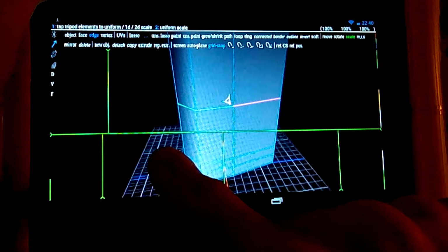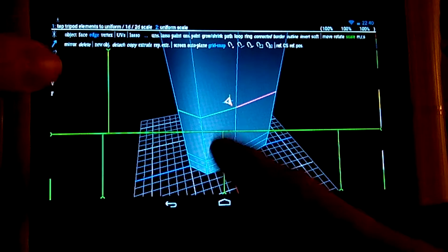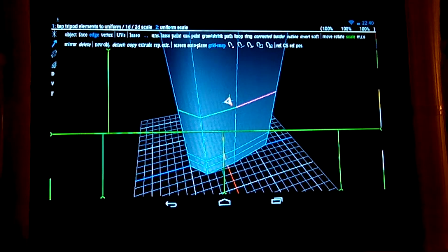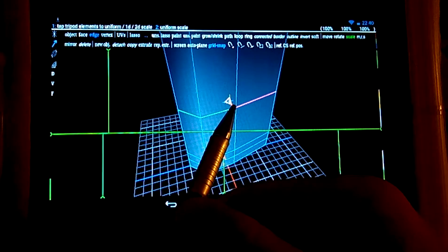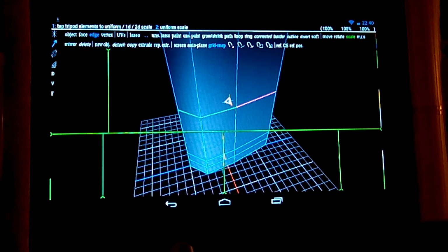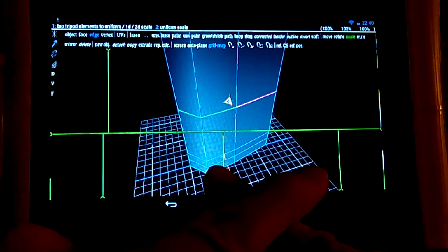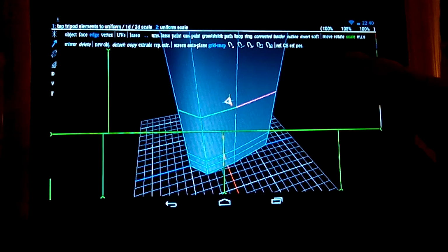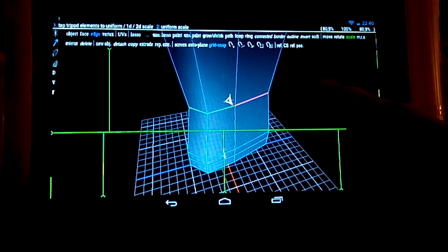Okay, I selected, maybe it's too little to be seen, the white line in the middle of the red and blue arrow. This will allow me to shrink or scale the section in the plane made by the crossing of the two coordinates. So let's shrink it to say 80% roughly.